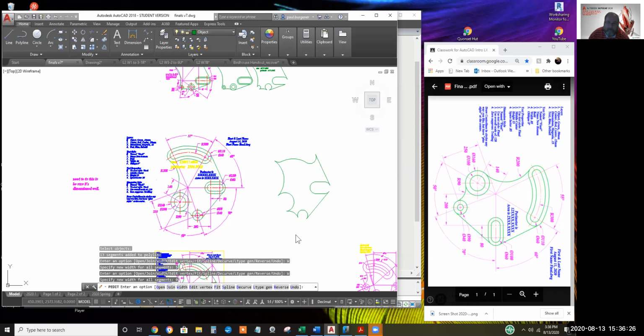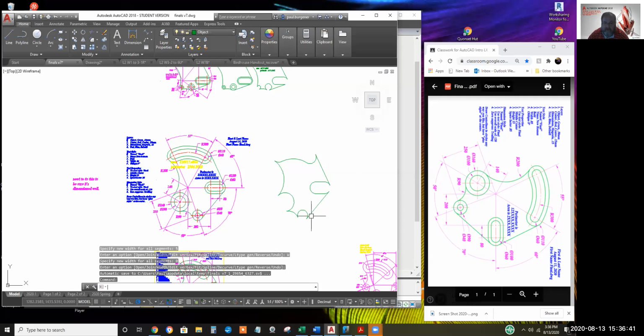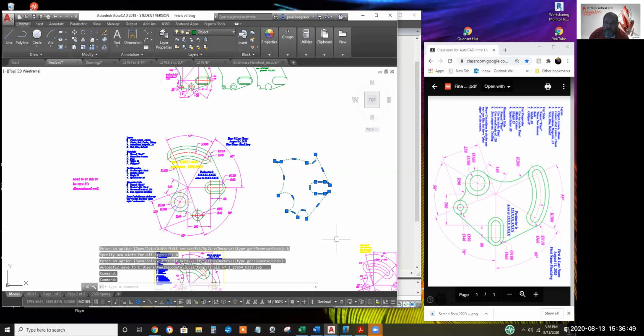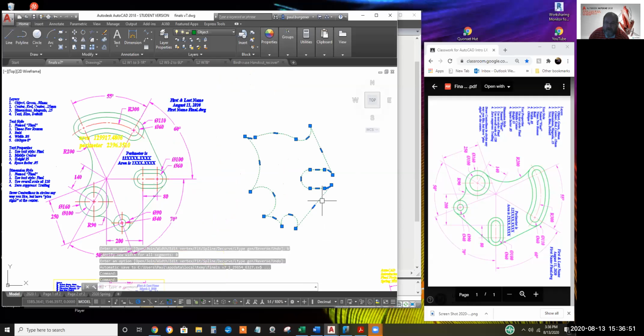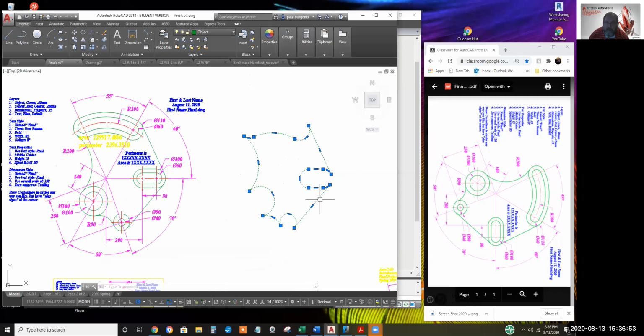So that's fine. We're done with the p-edit command. So I'll hit enter to, oh, no, I'll hit X for escape. All right, why does it not, there we go, enter. Not sure why mine didn't react. Anyway, click on this thing and sure enough, it's got the 14 segments all the way around. So it is a single object.